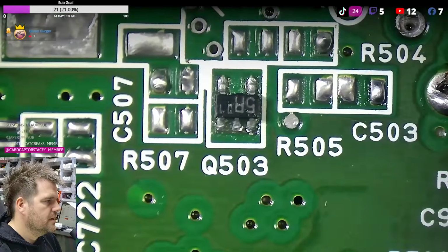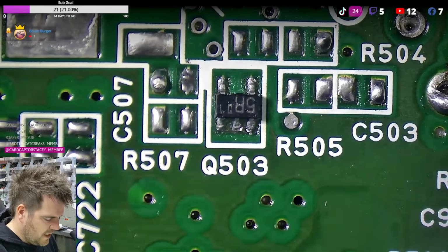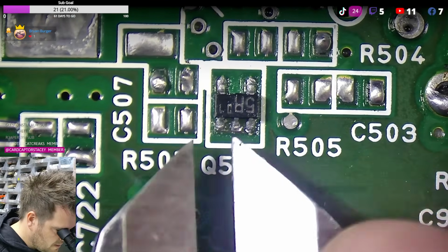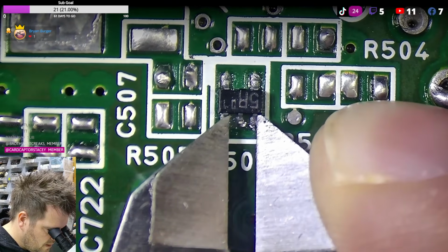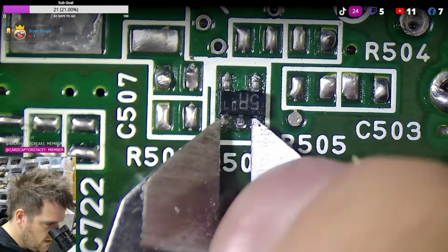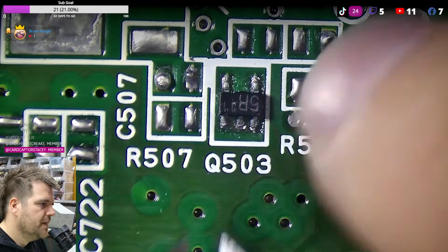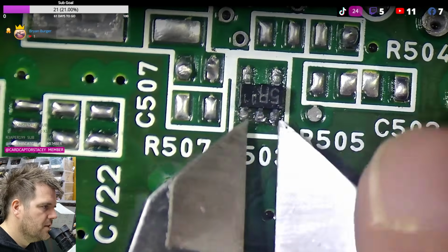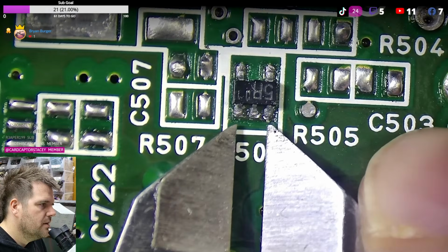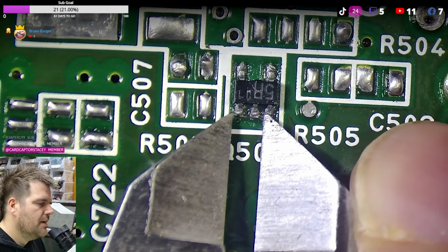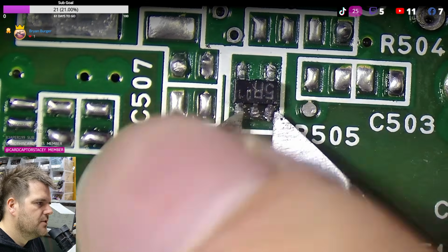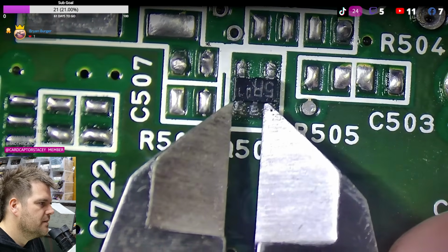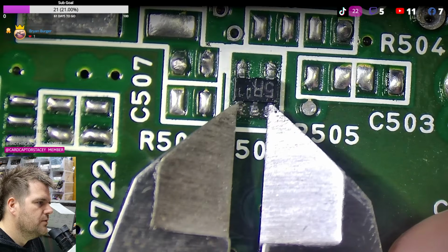So over here, what I'm going to do is, as accurately as I can, I'm going to get my vernier in here. I'm trying to look at the inner blade of the verniers being on the center line of the metal pad. So see the left tip? I put the left tip on the left edge of the pad. That's the center, and that's the right edge. So if you're looking at this tip here, I'm trying to get that central over that bit there.